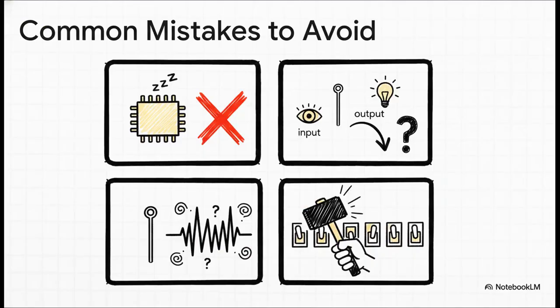Okay, before we wrap this up, let me give you a list of the most common mistakes people make. Seriously, watch out for these. Number 1, you have to remember to enable the clock for the GPIO port you're using. If you forget, the port literally has no power and you'll be pulling your hair out wondering why nothing works. Second, always double-check your pin modes. Third, don't forget those pull-up or pull-down resistors for your inputs, no floating. And last but not least, be really careful when you're writing to the control registers. It's easy to accidentally mess up the settings for other pins on that same port if you're not paying attention.